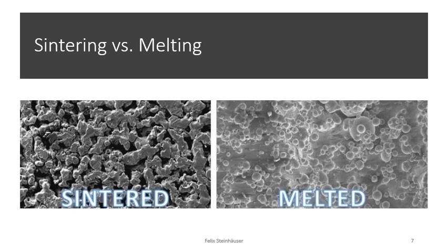So, without further ado, melting an object is really bringing a metal over its melting temperature, liquefying it, and then letting it cool so that you get a solid object again. In sintering, you try to fuse particles with a combination of pressure and heat without melting the material.